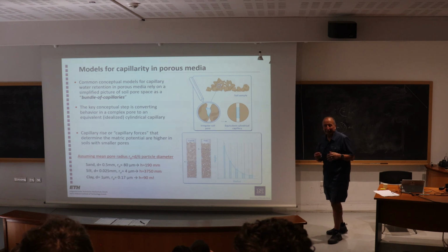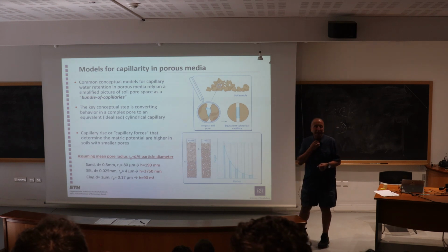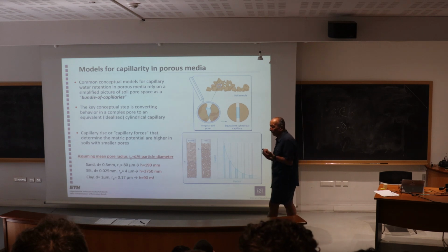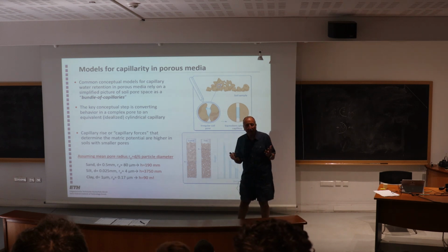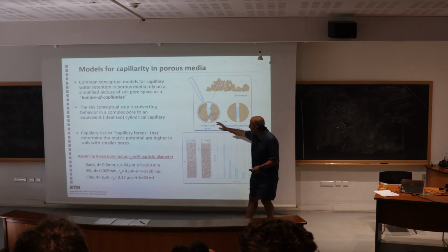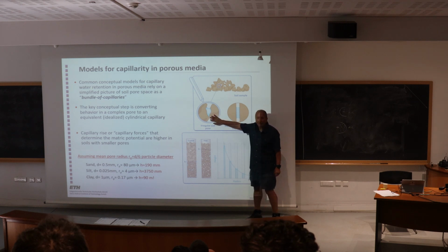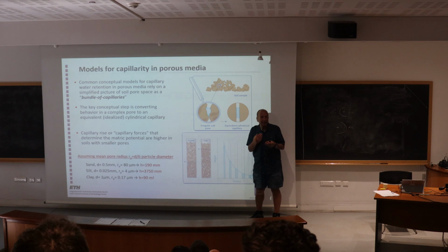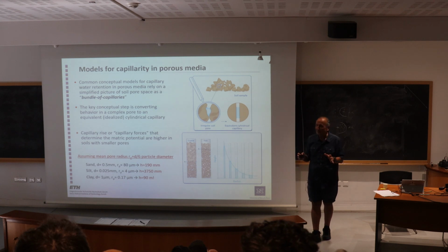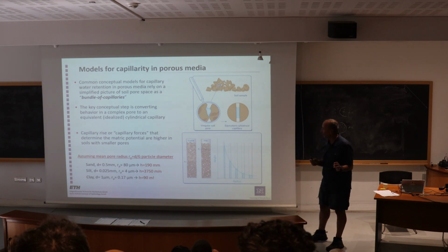Okay, so the capillary rise was actually still the model or the vehicle that we interpret capillarity in porous media. Of course, we are not naive to think that all pores in soil or in rocks are cylindrical, but we make some hand-waving equivalents, taking a pore of any shape, assigning to it some equivalent radius, and represent it as a capillary. So we do that with, I think, a bit too much liberty, but still, it is a useful concept.